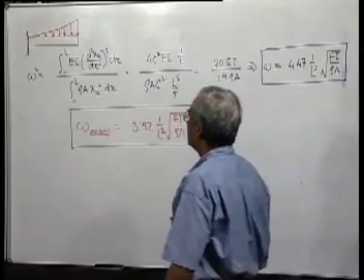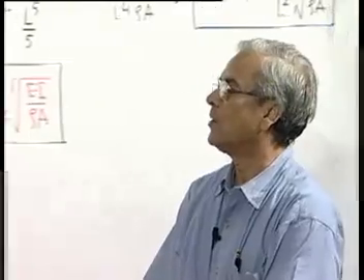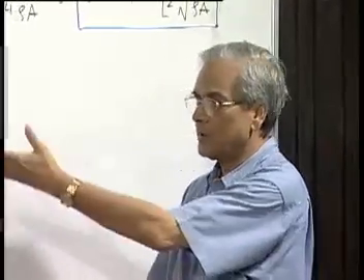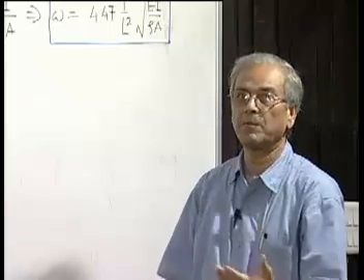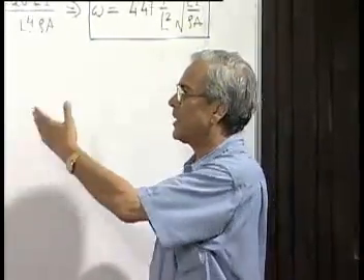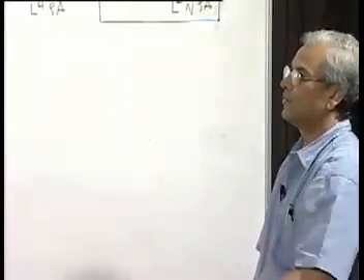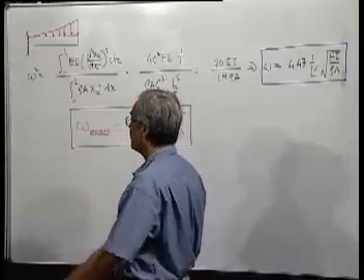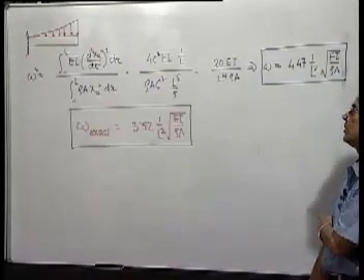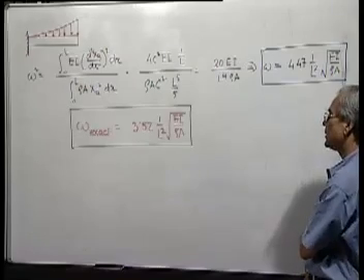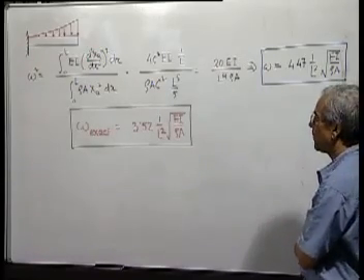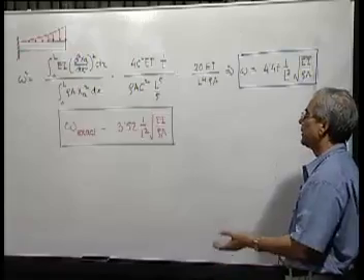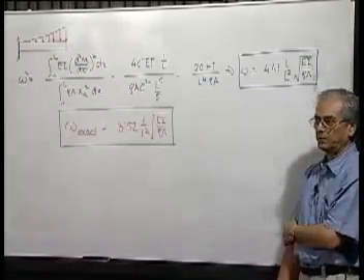So I think this will be enough for the time being, but we have to now keep in mind whether it is possible to find out the higher mode or higher frequency. In all these cases, Rayleigh's principle is valid in case of the fundamental frequency, as you know. So we are all the time assuming something for the first mode deflection. If we can find out the second mode shape and put it there, obviously we will get the second mode, but most of the time it is convenient to solve the problem satisfying the boundary conditions, which will give us the first mode frequency. So in the next presentation we will try to see if it is possible to get a methodology by which we can have some approximate values of the higher frequency.